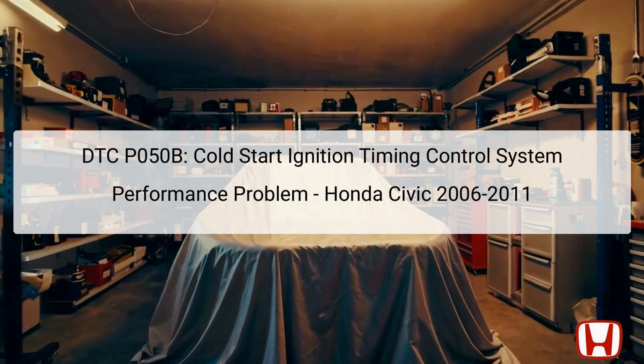The affected components include the crankshaft position, CKP sensor, which monitors the position of the crankshaft to assist in timing the ignition. Another key element is the throttle actuator control valve, which helps regulate air intake into the engine for proper combustion. Proper functioning of the intake air duct is essential to ensure the correct flow of air into the engine, while the MAF, mass airflow sensor, measures the amount of air entering the engine, influencing fuel mixture adjustments.